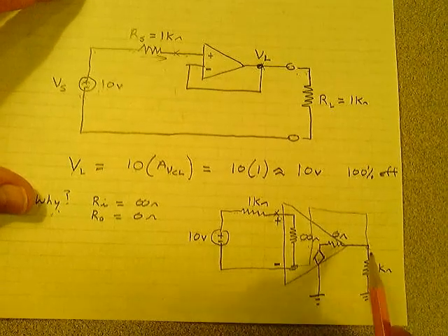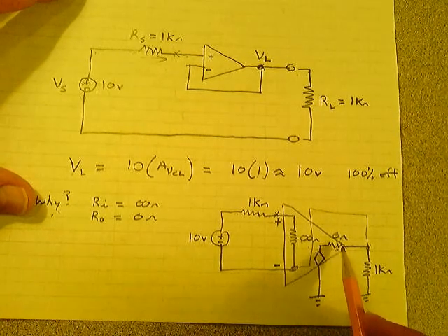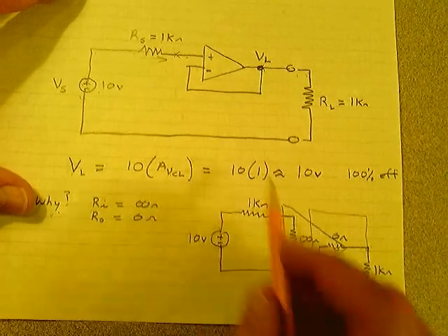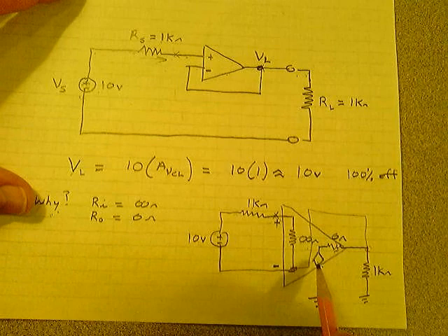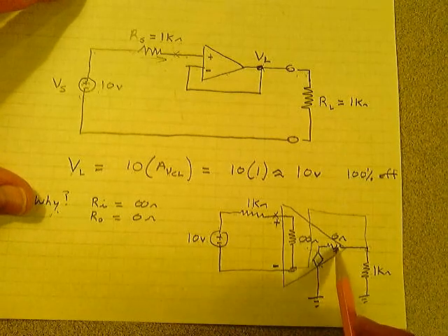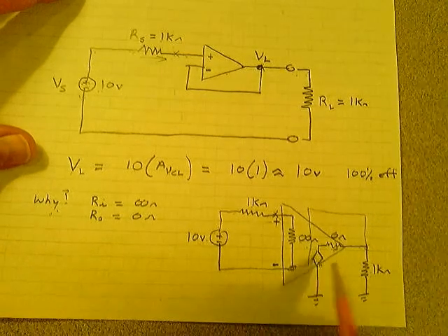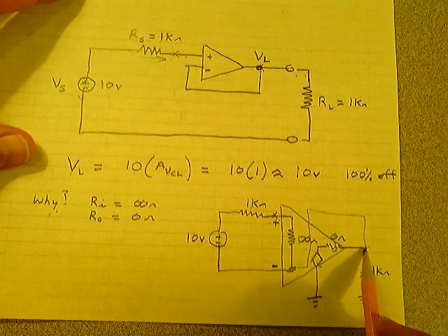And that being a Unity Gain Amplifier, because we have this connection tied to this connection, the output that's generated, that output resistance is very low, which is a really good thing because the voltage that's generated inside here all gets put out here, because of the same reason back here, except the reason is that resistance is very, very low. So you have 10 volts here, we'll say, times 1K divided by 1K plus 0. You get 10 volts there.